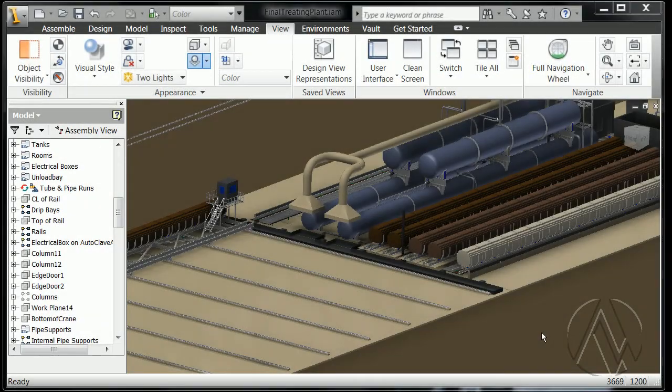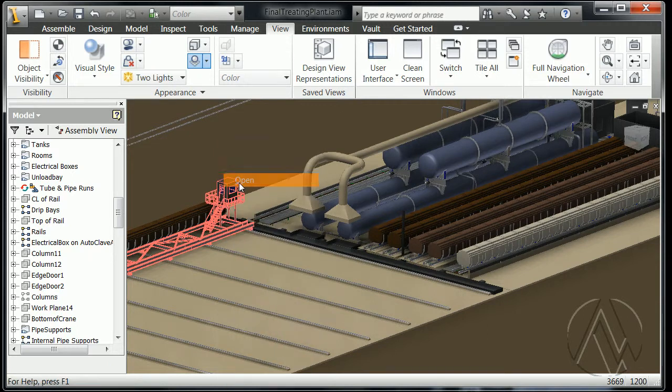Working with large assemblies has become a lot easier with Autodesk Inventor with the use of the substitute level of detail. I've taken an 11,000 component assembly and brought it down to 3,600 parts currently, and we're going to take more of a load off of it by taking the transfer deck assembly here and walking through the process of creating a shrink wrap level of detail.